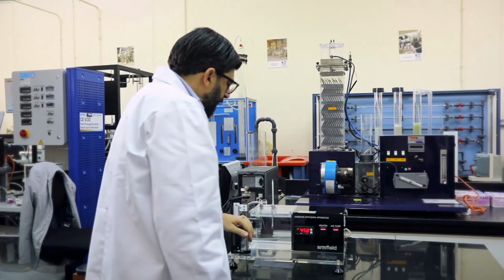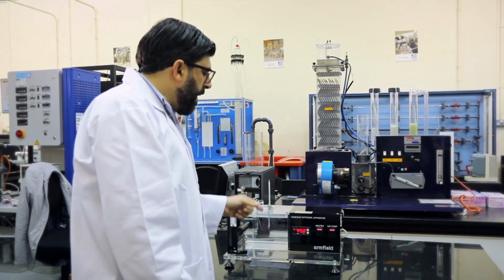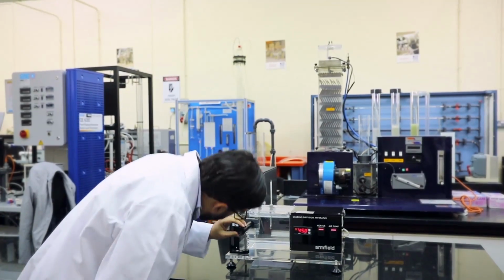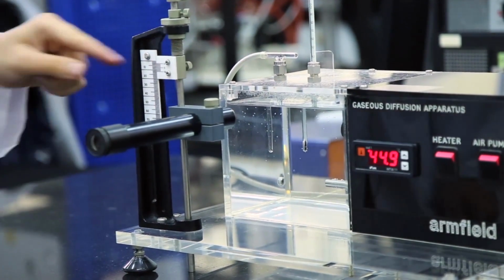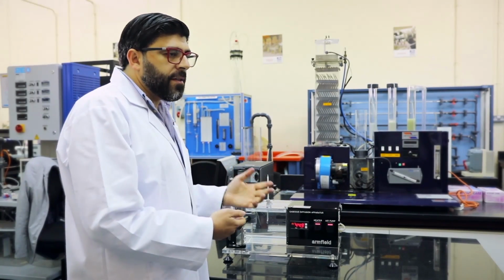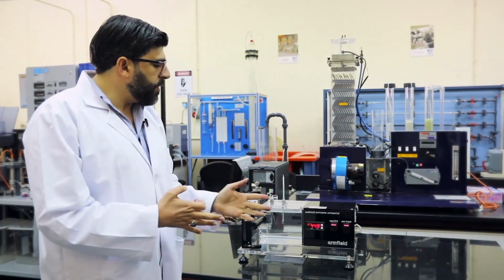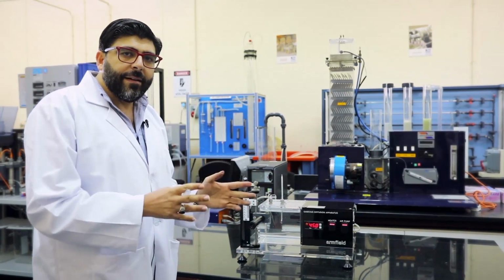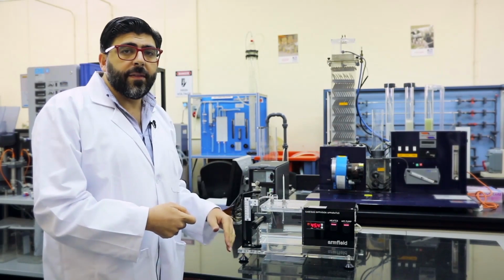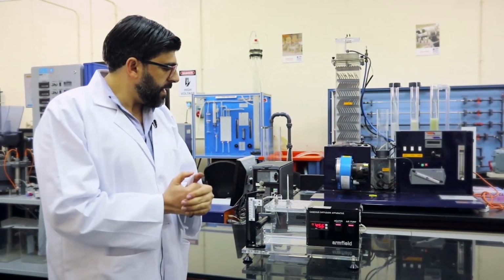And then with the stopwatch, just record the surface level and record the time, and wait until a certain time, then check the level again and record the new height with the new time. And that's it, until you get at least 5-6 readings, okay? At least take 5-6 raw data points, so it will be your final results. Then if you want to repeat the experiment at a different temperature, you can do it. So this is all about the experiment today. That's it. Thank you so much.